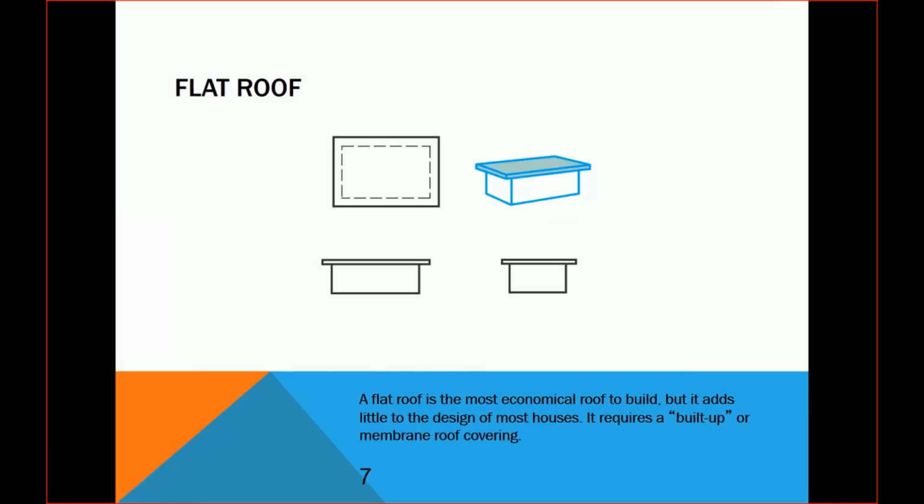Flat roof. No roof is ever completely flat. Keep that in mind. If we have a completely flat roof, you're going to have nothing but problems. Water's going to build up on it. It's going to eventually leak. All roofs have a little bit of slope to them. Also, for a flat roof, you're going to use a different type of roofing material. You will not use a shingle. Usually it's a built-up roof. We'll talk a lot more about that in the commercial class.